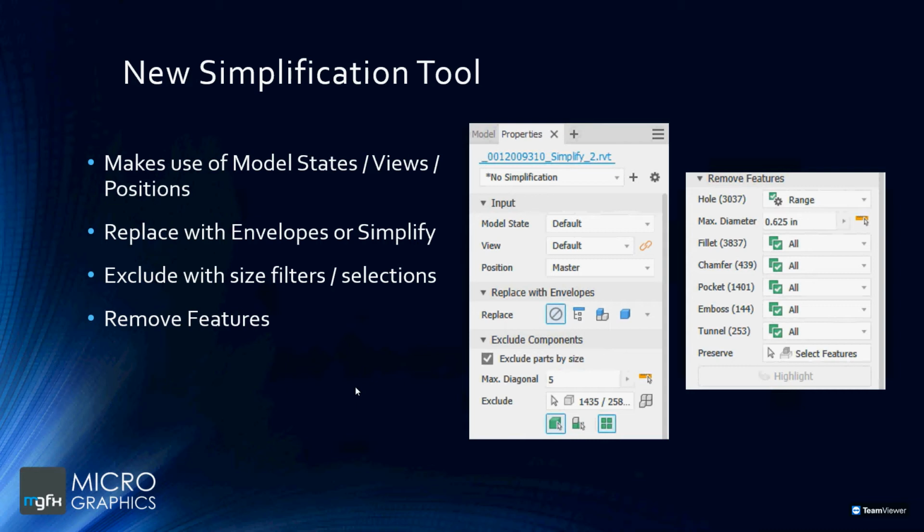Revit makes use of basic geometry to allow for large-scale projects to run smoother. So if I have to use an example in Revit, you would have a simple reference of a window. But if you did a cross-section, you may not see the actual cross-section of the aluminium extrusions that are used to make the window.